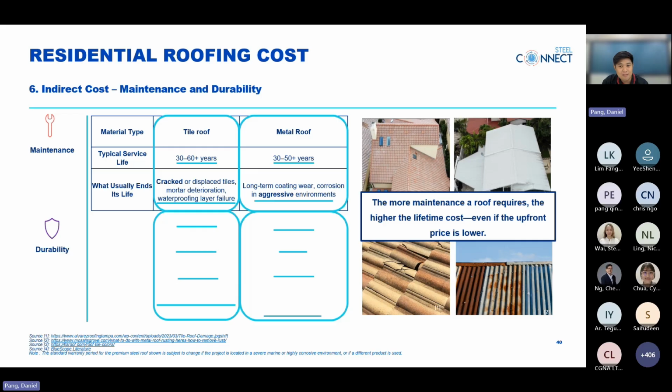Tile roofs are less predictable because tiles can crack or break unexpectedly due to impact, maintenance activity, or even movement. Following on serviceability, tile roofs are fragile to work on, and replacing broken tiles often takes more time and requires greater care to avoid further damage. Lastly, on warranty coverage, tile roofs are given a 5-year system performance warranty, which is short considering the price you pay for the roof.